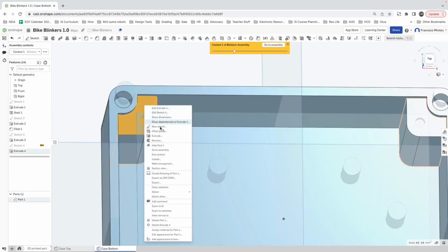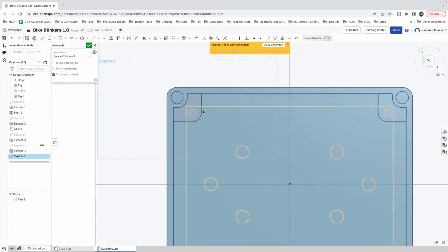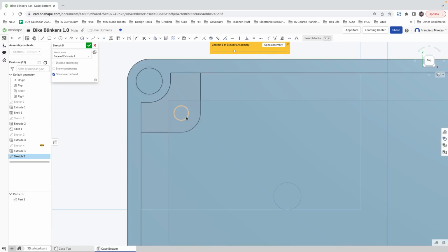Then in here, I'm gonna make a new sketch from the top. I can project. I think that's... or yeah, I can. No, I don't need to project actually. I can just make a circle based on the radius because they were concentric.